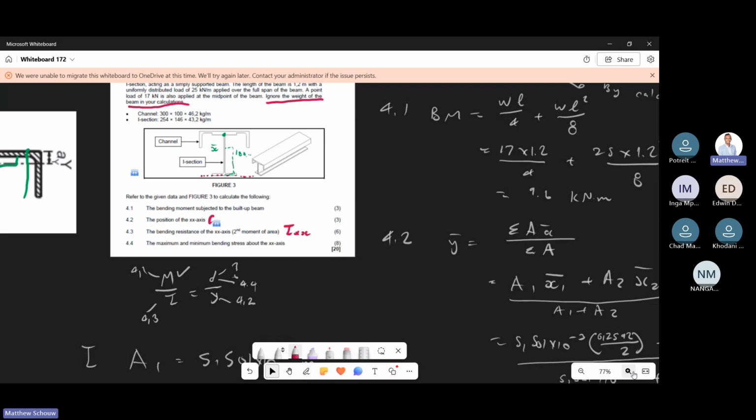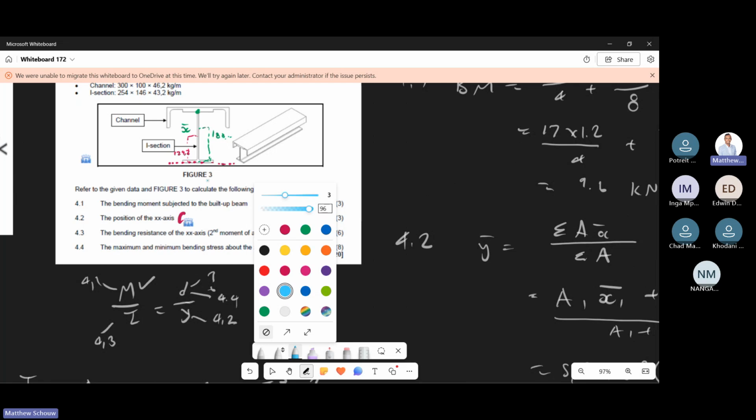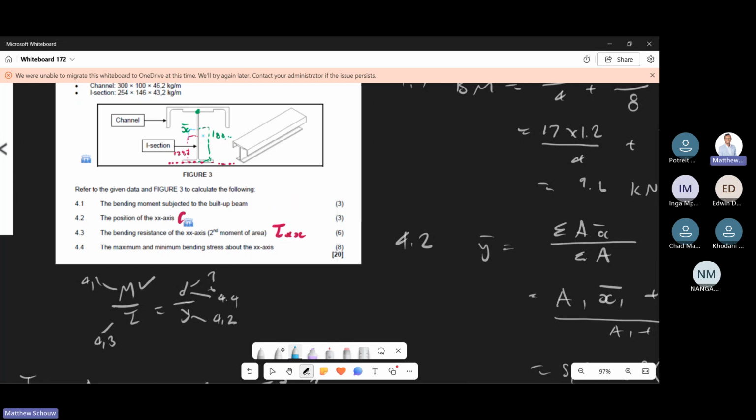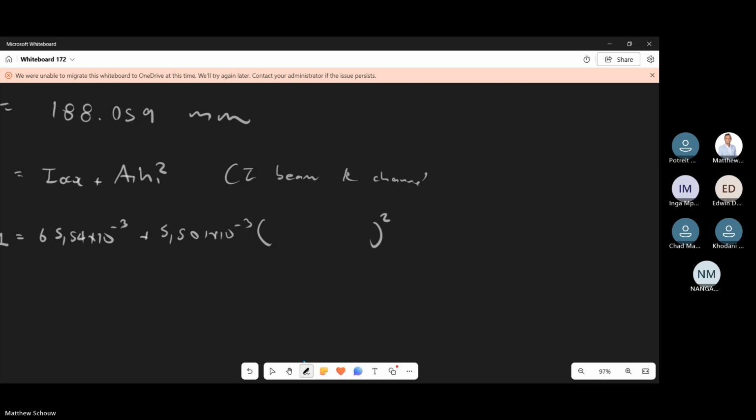So I'm going to draw this. The center to the element itself, the first one, is 129.2, right? So the distance we need is from here, the blue one. It's basically 188 point something minus the 129.2. Is that clear to everyone? That's what that H value means. Porter, can you give me the values again? It's 188, the centroid.